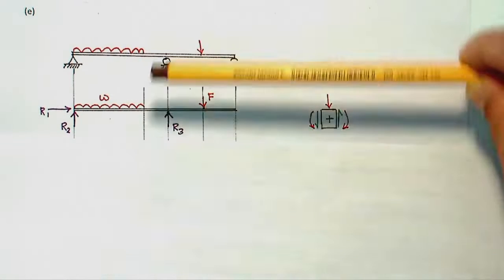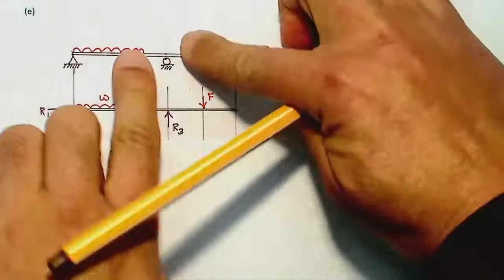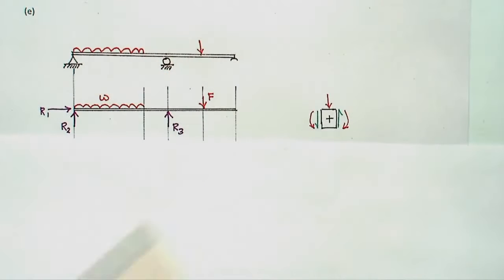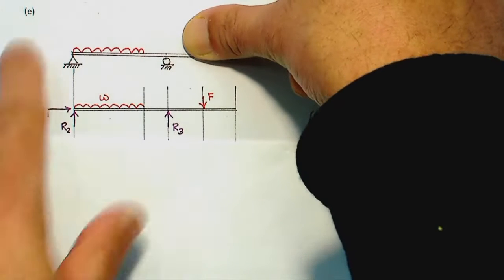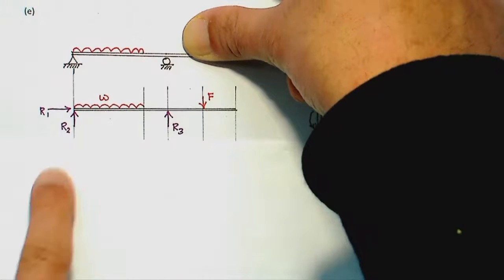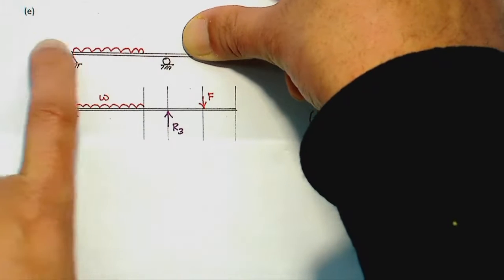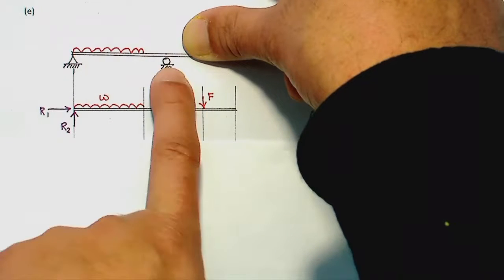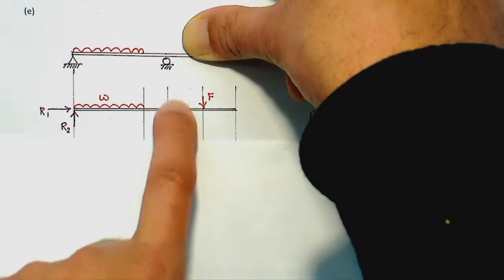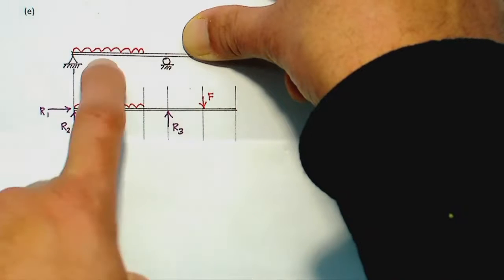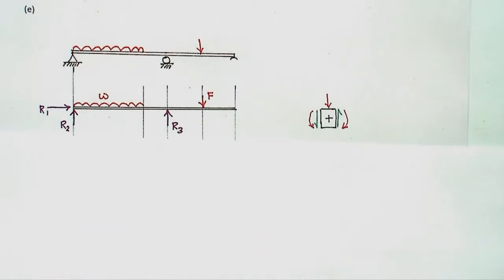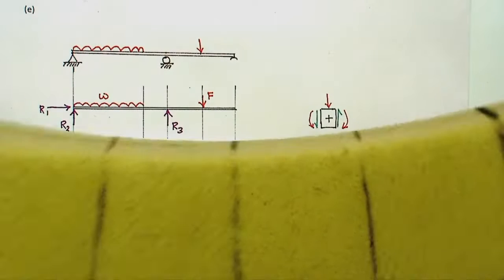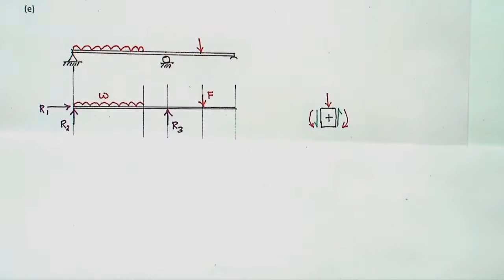Why? Because if you consider two sets of loads separately, if you don't consider the point load to start with, let's say you have got the UDL, then the reaction force would, of course, this UDL would be supported by these two. So both would be upward. Okay, because the load is in between these, and the beam would deflect in this way, right? The beam would deflect that way over this span.